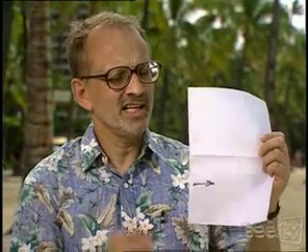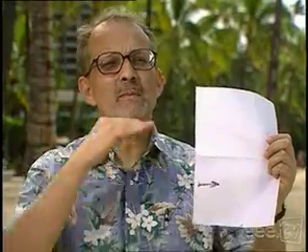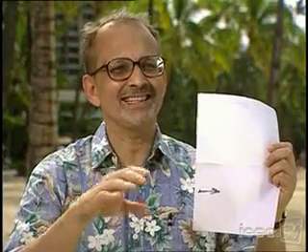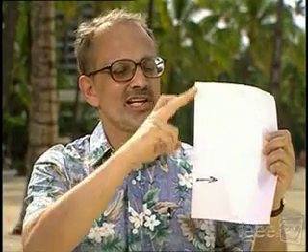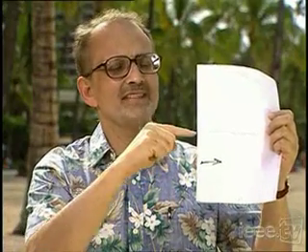So the algorithm or the systematic procedure by which you can encode a piece of electronics to search for that to some accuracy is often called binary search. You proceed by bisecting or halving the full scale. So here's your full scale, here's the midpoint. Now you have to calculate the midpoint. That calculation is being done in analog circuits.